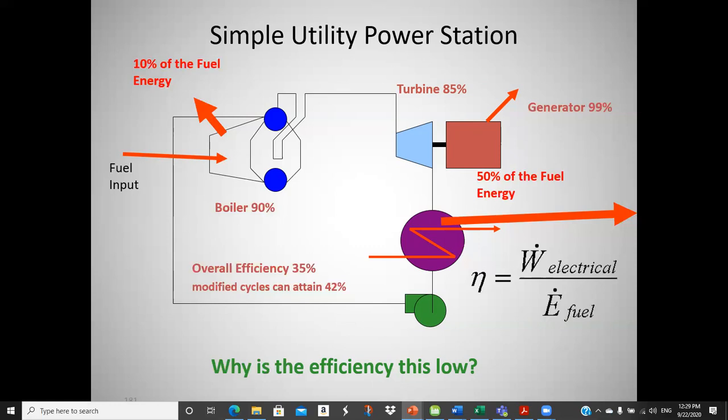No, it's just that when they pulled that pressure down so low coming out of that turbine, the temperature is only about 110 degrees Fahrenheit. But most of the fluid, the working fluid, is still steam, and steam at 100 degrees still has a lot of energy. It's still 1,000, 1,100 BTUs a pound.